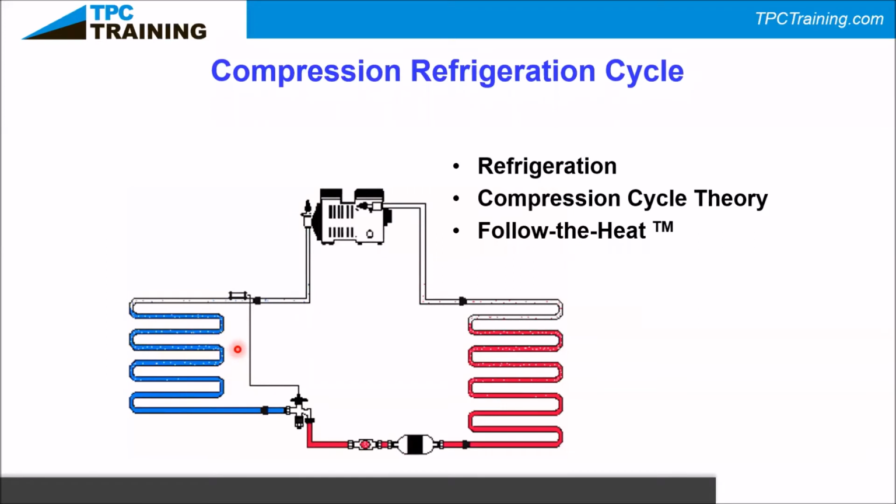This is the evaporator. This is your indoor section. So I'm taking air that I want to condition and moving it across this evaporator, causing the heat to be absorbed into the refrigerant as a low pressure, low temperature liquid starting here. And as we see these dots flashing in here, that's the refrigerant flashing off and becoming a vapor.